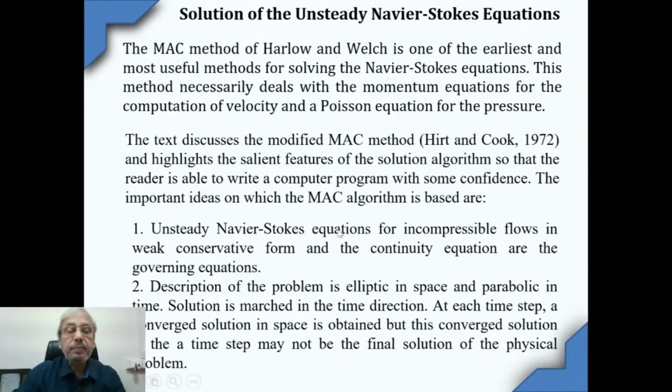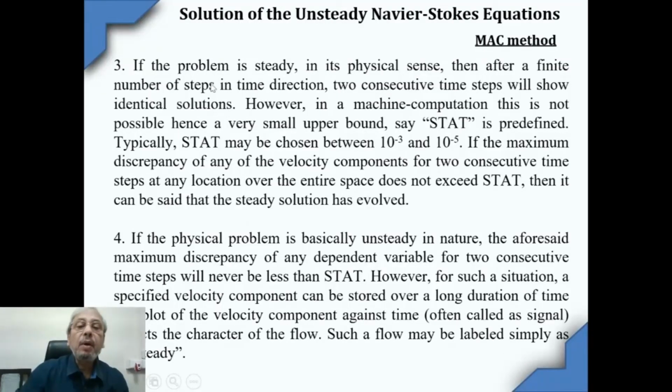At each time step, a converged solution in space is obtained, but this converged solution at a time step may not be the final solution of the physical problem. If the problem is steady in its physical sense, then after a finite number of steps in time direction, two consecutive time steps will produce identical solutions.